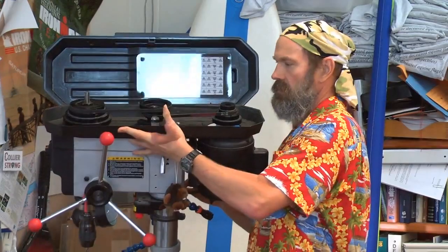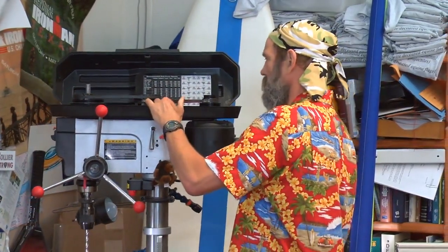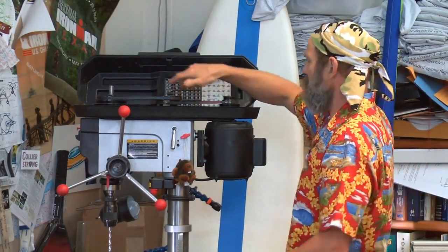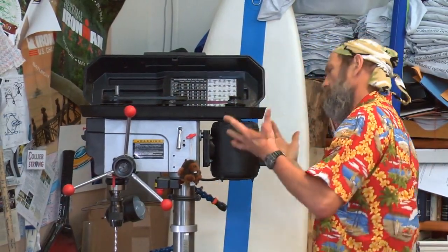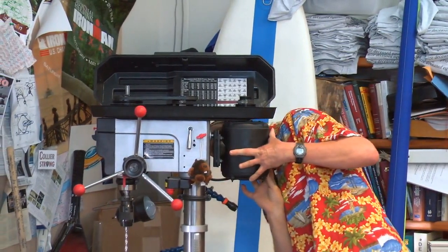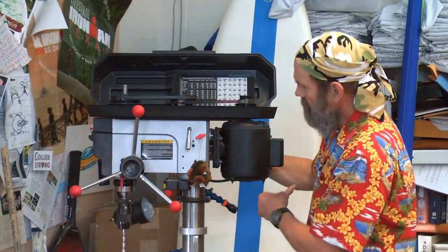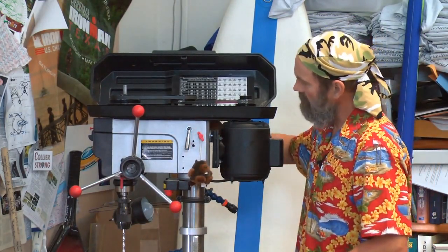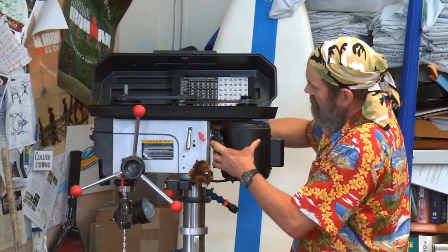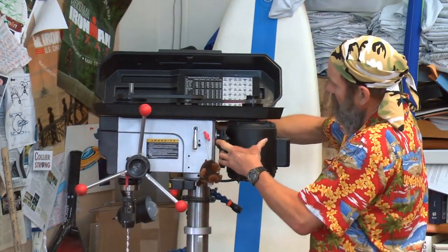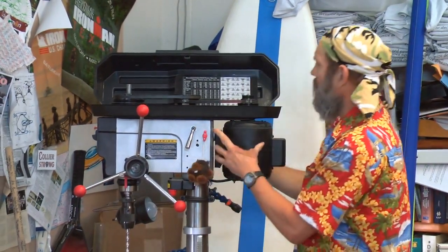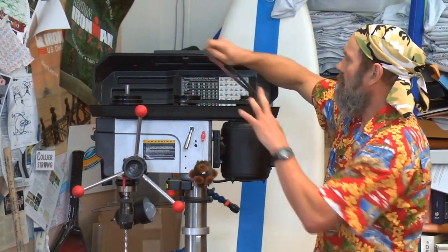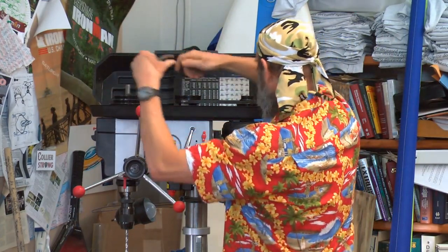Right? How do I change the speed? There is no idler pulley here. Everything is just the tension. And you look at this device and you say, how do they change things? Well, it turns out, see this red knob here? If I loosen that, see I'm pulling and I can slide in and out. That loosens everything, so the belt comes off. And I can change the pulley diameter as I'm running on.